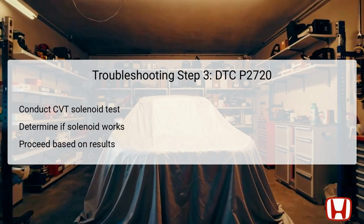The third troubleshooting step involves testing the CVT lockup clutch control solenoid valve to ascertain its operational integrity. This valve regulates the engagement of the lockup mechanism, which contributes to fuel efficiency and performance during higher speeds by eliminating slip in the transmission. The technician will conduct a test of this solenoid to determine if it functions correctly.